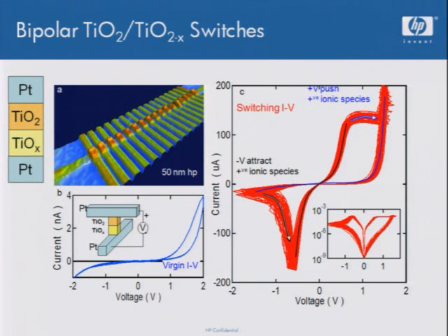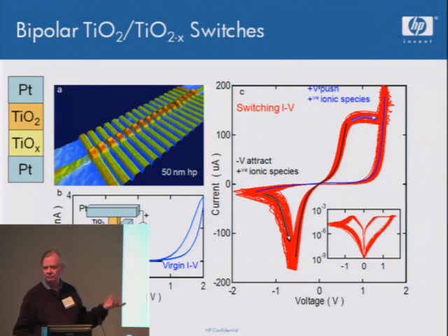If you measure resistance at low voltage, the resistance change typically for us is about 3 orders of magnitude, but that's just convenient. It can be as high as 6 orders of magnitude easily. It turns out that that's not necessary, but you can make this resistance change effectively as large as you wish, if what you want is some sort of a binary switch.